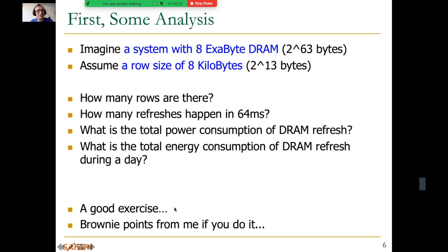You can probably find the solutions to it also somewhere online in the digital design and computer architecture solutions. But my point is refresh is consuming a lot of energy, especially if your DRAM size is larger, and especially if your refresh rate frequency is smaller. And this is really wasting energy. There's no point in wasting this energy.